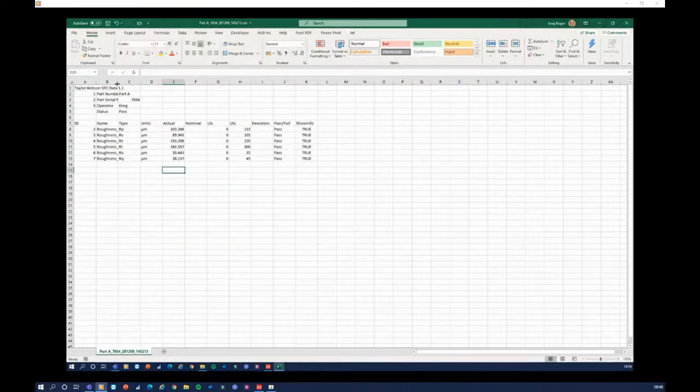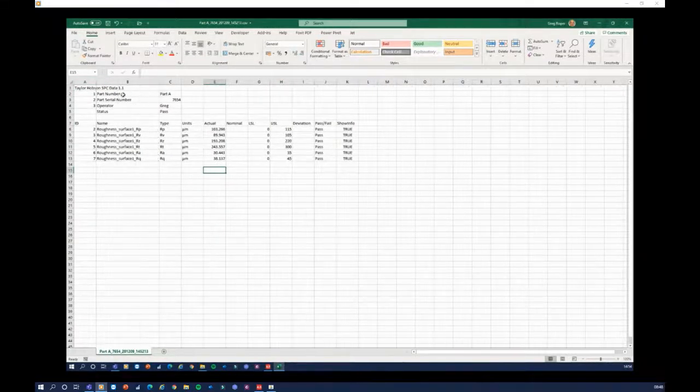So here's all of the part number and all the value information that we've related and we put in. Here's the status that it's all passed. Here's the results and the parameters and the units. Here's the actual parameter results. Here's the upper and lower tolerances that we put in there, whether it's passed or failed and whether that's true or not. So we can then use that file for doing any further SPC work that we want to with that particular CSV file.